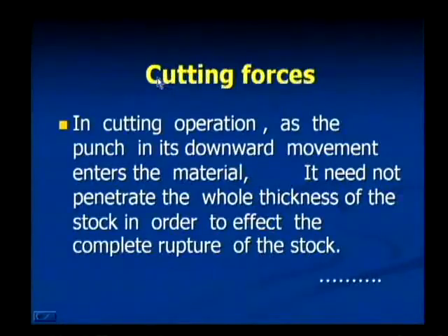Now, let us discuss cutting forces. In a cutting operation, as the punch in its downward movement enters the material, it need not penetrate the whole thickness of the stock in order to effect complete rupture of the stock. If T is the thickness of the stock material, the punch need not cut the stock throughout its thickness T. If it penetrates a part of the thickness, that is sufficient for the rupture or failure to take place.